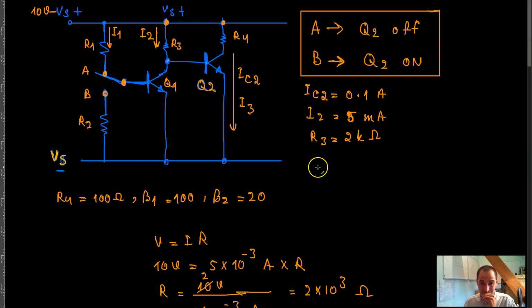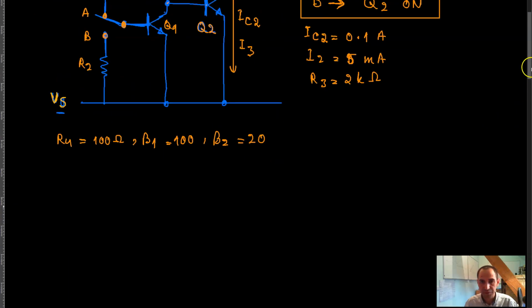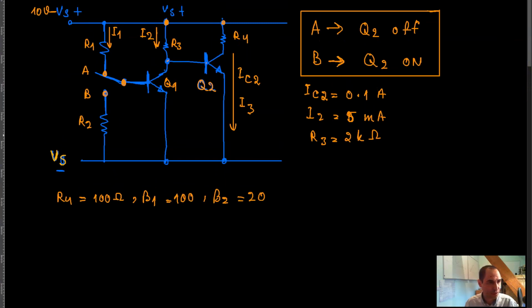Now, one thing that you need to take into consideration is that now that we have chosen this resistor for this branch, the current for this branch remains essentially 5 milliamp whether we like it or not, right? That means that this transistor, sometimes it's turned off, sometimes it's turned on.